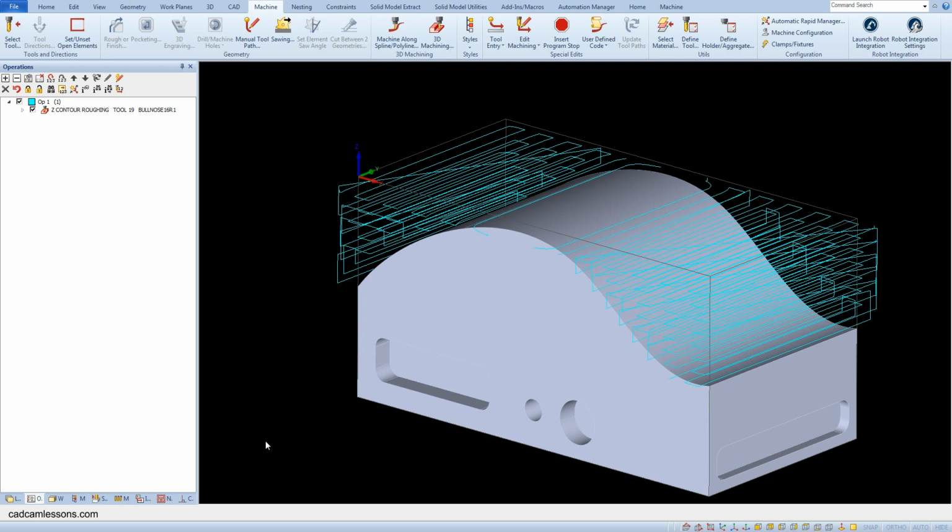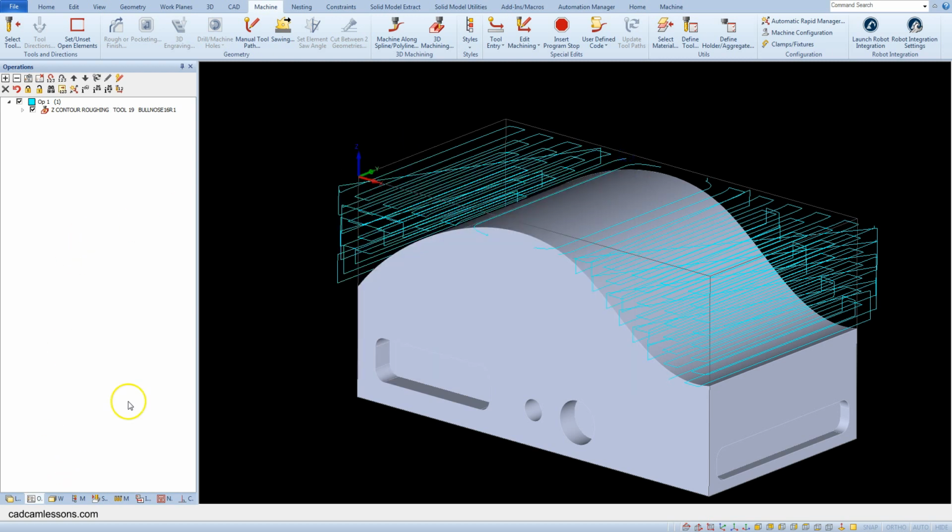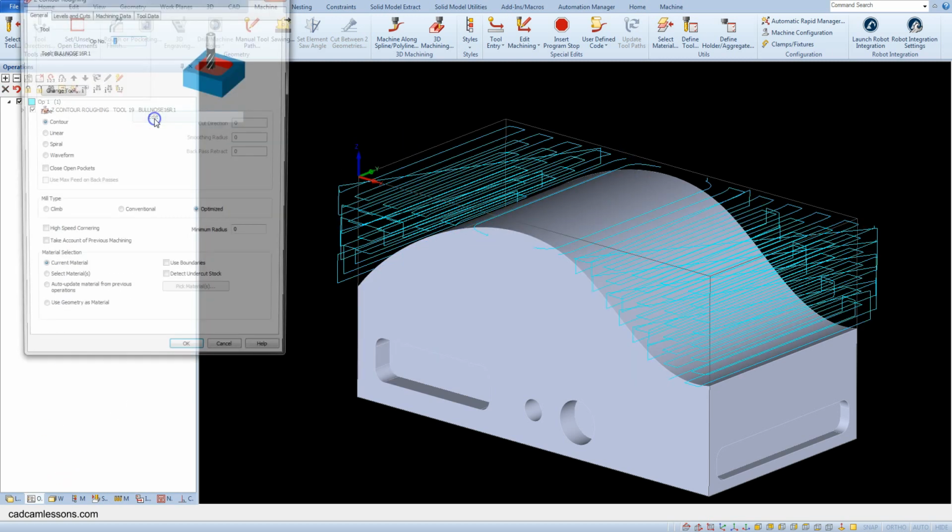At this point, the height of the steps that remain after roughing is a bit too high to go to finishing. We can get smaller steps in two ways. The first is to change the step in z-axis, but first let's check how long this machining lasts. It is 16 minutes.